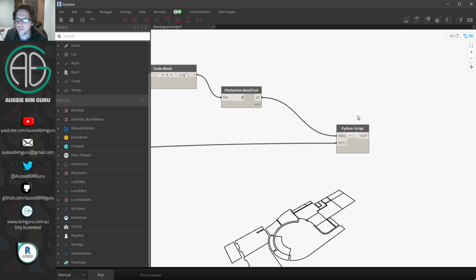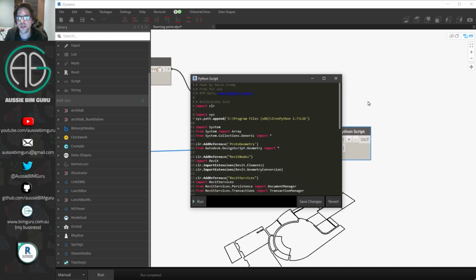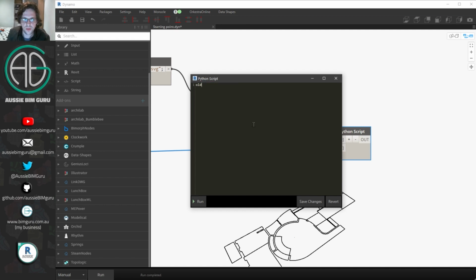leader on each line. So we're going to be using an iterative function, which means we're going to keep going through one at a time on each string, and we're going to be replacing each occurrence of something each time we run a replace routine. So we know that we can go line after line and replace each of those with a successive list of replacements, which sometimes the replace node for strings doesn't do well in Dynamo. So the first thing I'll do is define my old string. What's my old string? My old file contents. And this is the input at index 0. I'm then going to take my replacements, or I'm just going to call it replace at input index 1.